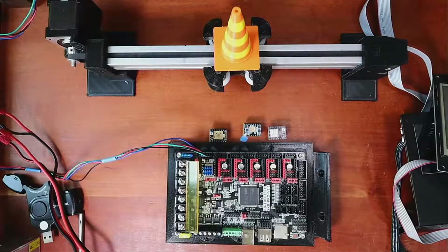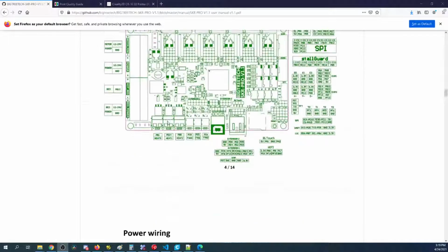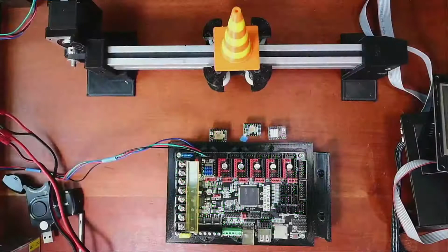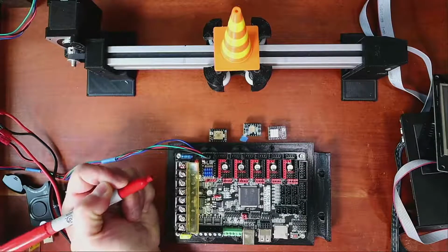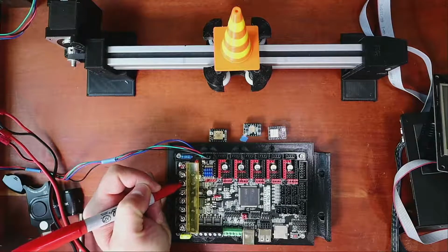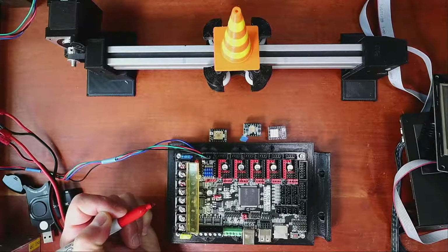I'll show you why that's important by going over to the web browser for a second. Up here, they talk about what the voltages are. So we need to know where plus and minus are. I'm going to mark the actual board with where the plus goes. So I'll go back over to the desktop real quick. And we know that this is voltage, so we'll mark it red. That way we know and don't plug in something wrong. Then they have the next one down here as red as well. That's voltage, and that's for board power supply.